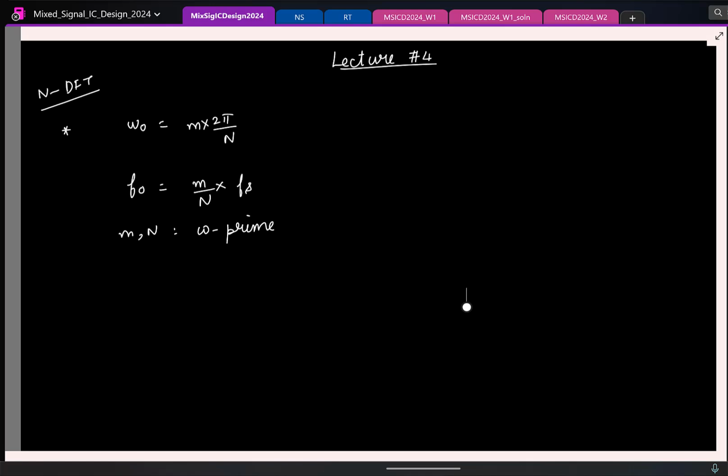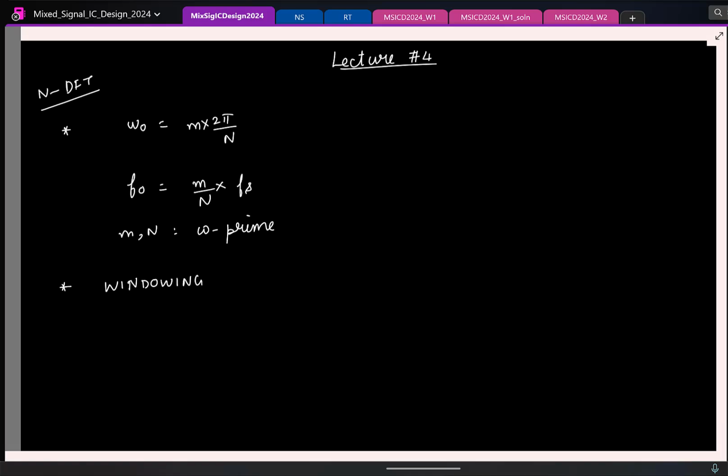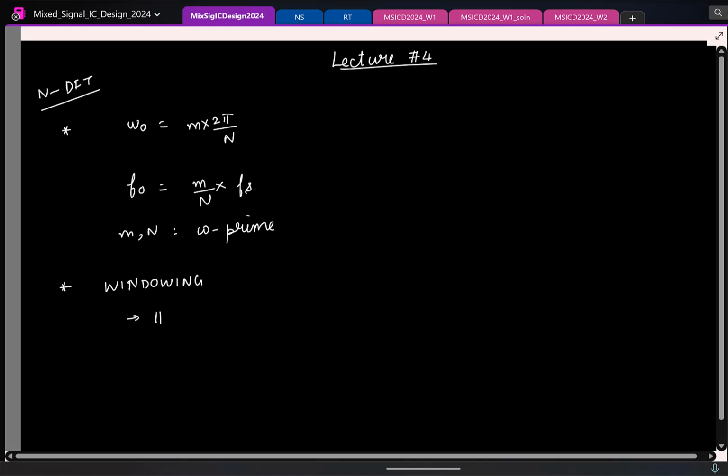And the solution to reduce the spectral leakage is, as we saw, windowing. Again, the reason is when you have a signal that is not falling on a bin, and when you take an endpoint sample, the sinusoid will not complete an integer number of cycles within the chosen endpoints. So which means when you form a periodic repetition of the signal, you will have abrupt jumps around the edges. So the notion behind windowing is to basically smoothen down those abrupt jumps, right? And two commonly used windows in circuits are essentially Hann and Blackman-Harris, and we saw the downsides of using windows.